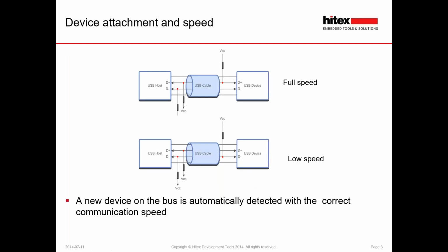So in USB device, when we have a microcontroller that has a USB peripheral, it essentially contains the USB physical layer, and we have simply a couple of pins, D+ and D-, for the communication channel. In addition to that, we would have typically an external component, a pull-up resistor, that's connected to one of the signaling lines, either the D+ line or D-, and this basically tells the host what the signaling speed is going to be.